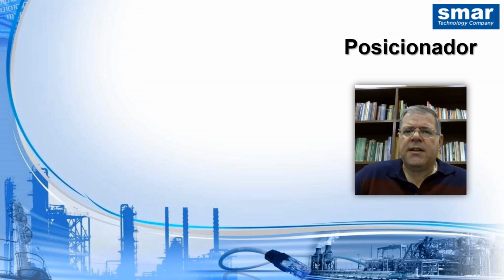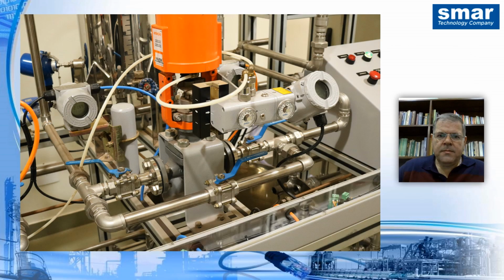It is a linear valve, and we will receive feedback from this valve using a magnet and a Hall sensor. The magnet will be fixed to the valve. It will operate the valve, so the Hall sensor, an electronic sensor, will determine the precise position of the valve as indicated by the main controller and maintain the water flow at the desired position. We show here again the valve with the positioner, which is, after all, a very important element in control loops in industrial automation.